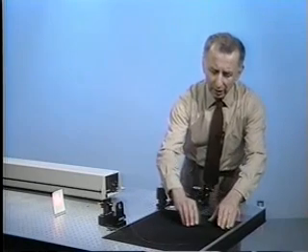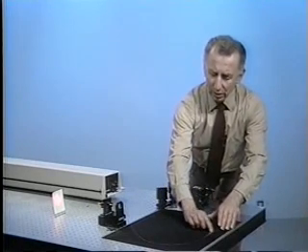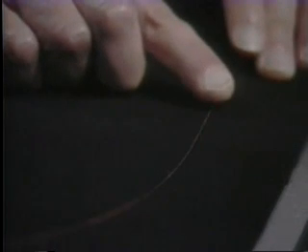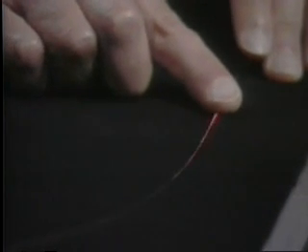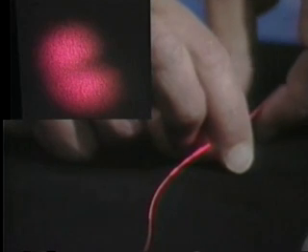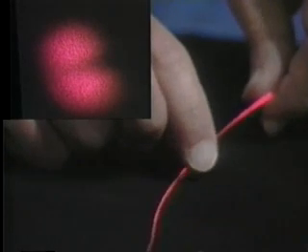In fact, if we take a look at the fiber here, as soon as I just press on it, if we take a close look at it, I can kick light out. If I just simply press on it, I can kick some light out. So it's very touchy to stress and to bend. What I would like to do then is show that I can kick out some of the transverse modes by simply bending or stressing the fiber.